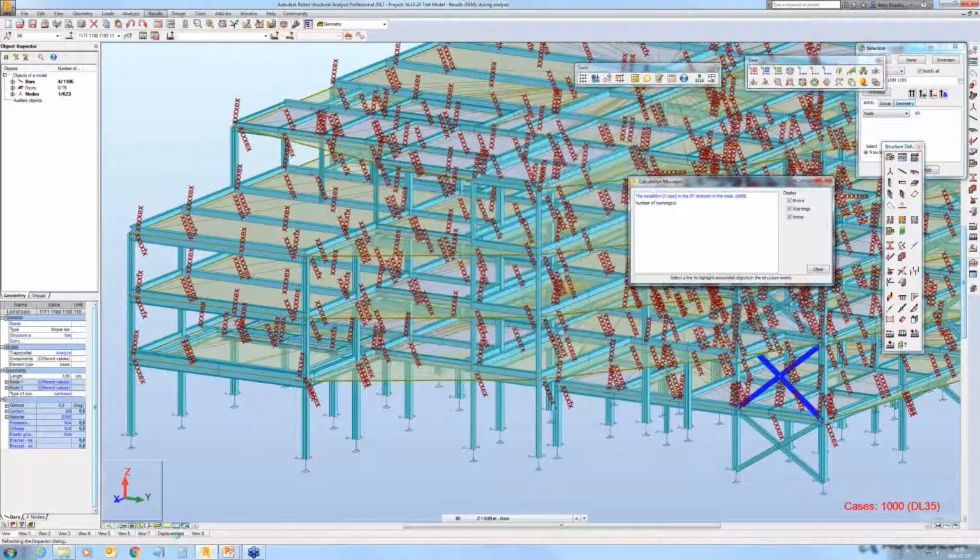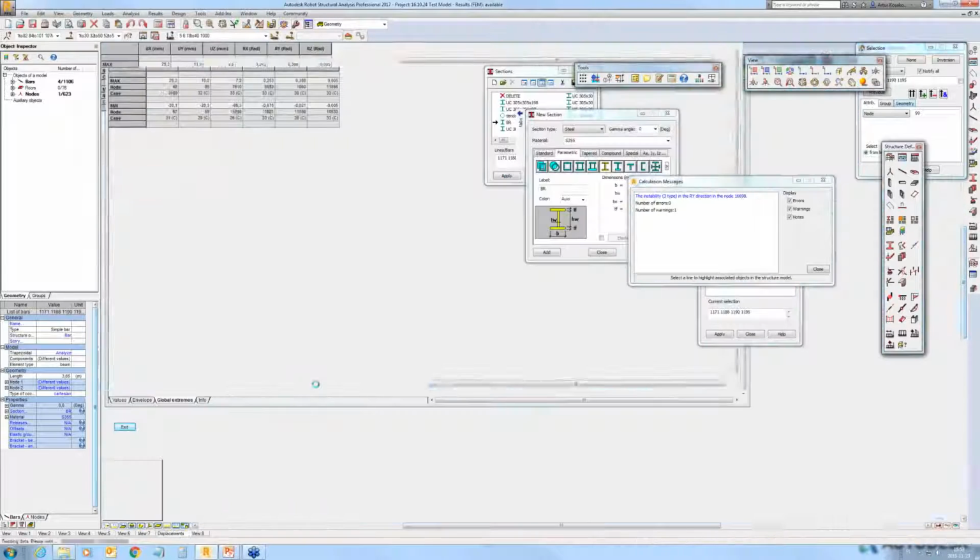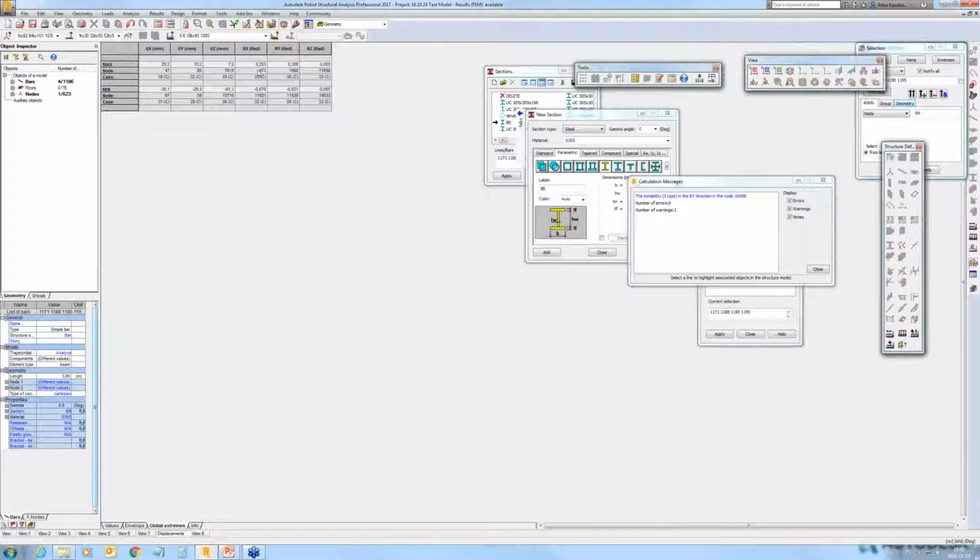So if we go to the displacements, as you can see, the instability is no longer reported in node 99 as previously, so that's a good sign. If we have a look now, we can see that okay, the values are smaller.